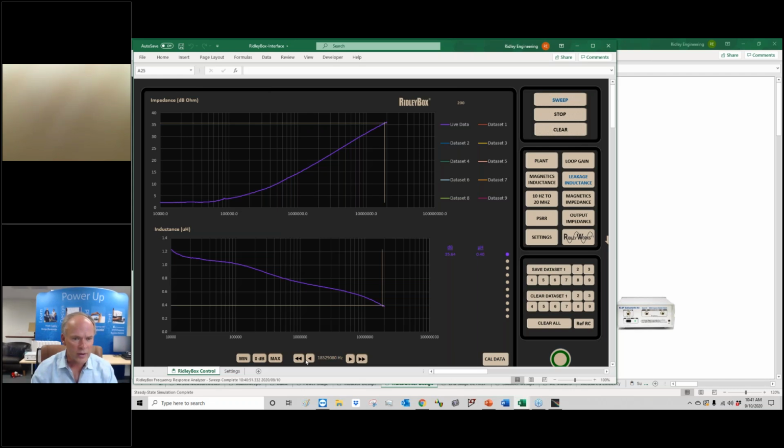And let's run our cursor across that. So we start at the max value. It's not max, that's min. Oh, sorry, we're not going for the max value, let's go for minimum value. Over at the left here, we see this starts out at 1.1 microhenries. And then, clicking right with our cursor, we see this down to 1 microhenry at 129 kilohertz.